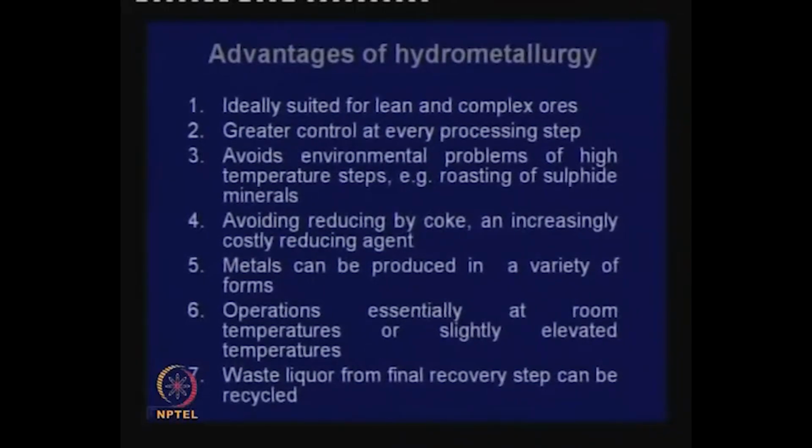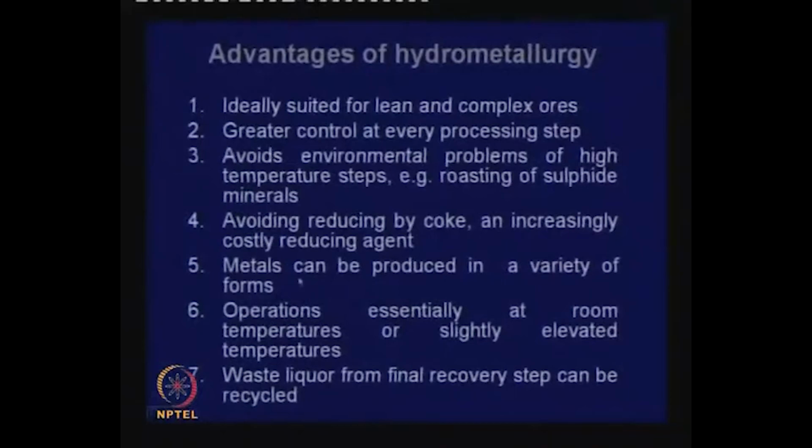It does not mean all hydrometallurgical operations are very clean environmentally, because many of the operations also reject slimes, they reject effluents which are also not good for the environment. Metals can be produced in a variety of forms, not liquids of course, but the solids can be in crystalline form, in powdery form. Sometimes we can even produce particles of given shapes, as we do in the case of nickel, when you reduce nickel amine solutions by hydrogen.